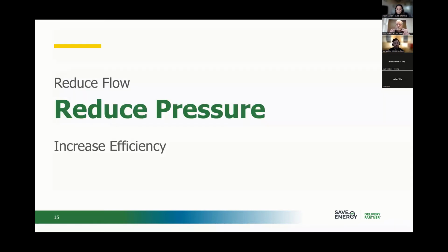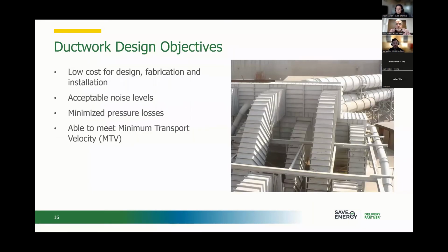All right. So we'll move on to reducing pressure. So Vern, I'll hand it back over to you for the ductwork design. Sure. Thank you. So what you're looking at on that screen is a complicated ducting system for a steel plant, and in the industrial world, the big thing is having enough velocity that you can carry particulates away. And every process will be a little different if you're dealing with wood products or steel products, and who knows what, ash in a power plant there.